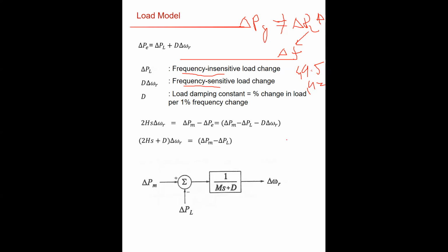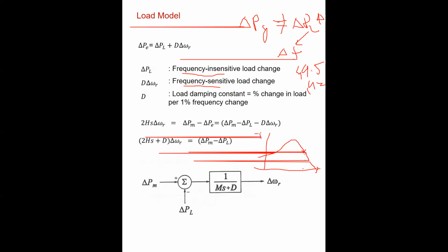And if you remember, if you take the induction motor, this is the torque-speed characteristic for the induction motor, and this is at synchronous speed here, right? And let's say this is your operating point here, and this is your torque, right? And if the frequency drops, then the torque, the power drawn by the machine, is going to change here.